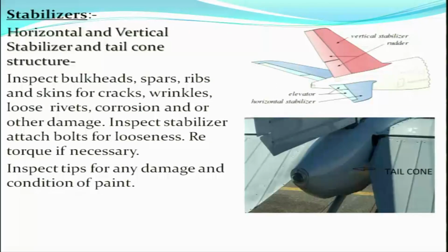Inspect tips for any damage and condition of paint. The tips, the horizontal stabilizer tips and the vertical stabilizer tips are to be inspected for any damage and the condition of paint.